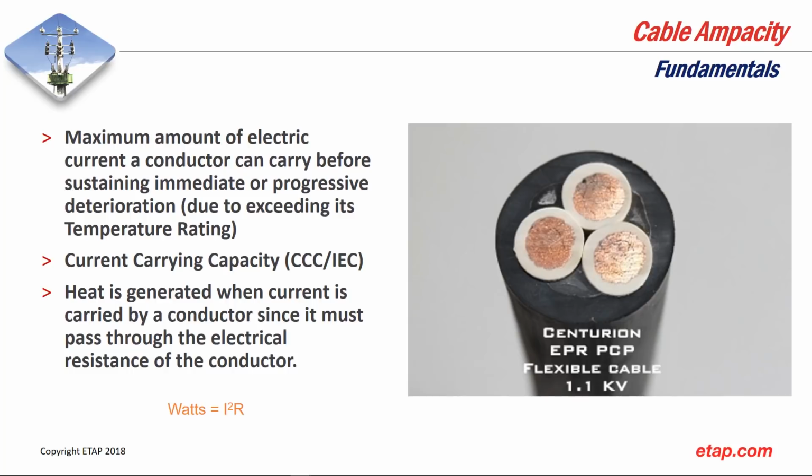As all of us know, proper sizing and current derating of cables makes sure that they operate to their maximum potential while providing secure and reliable operation. So let's start by providing the fundamentals, which is the cable ampacity, which is essentially the maximum amount of electric current a conductor can carry before sustaining immediate or progressive damage over time due to exceeding its temperature rating. So it's very important to properly derate and size cables, otherwise we shorten the life of the equipment.